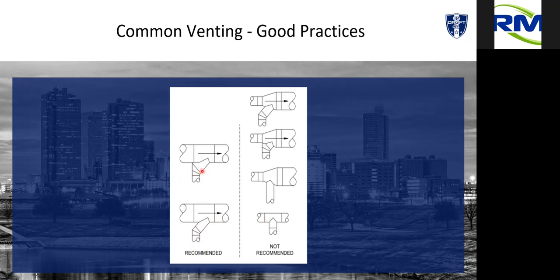Now, a boot tee is similar. It's not identical, but it is similar. So if you have all of the room to do it, lateral tees are the best option. If you don't have the space, boot tees are the next best option. But in reality, these two are not the same. So if Steve and Austin and his staff design a system with lateral tees, and a contractor tries to specify or tries to use a boot tee as a quote unquote same fitting, that is not accurate. Okay, so just keep that in mind when you're looking at designing systems, that a lateral tee and a boot tee are two different things.